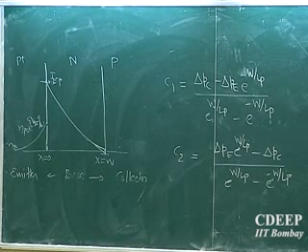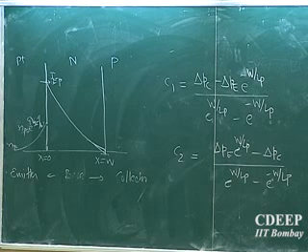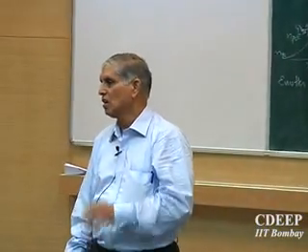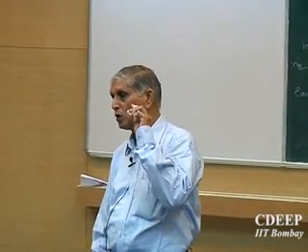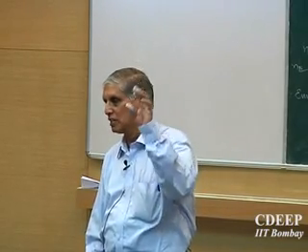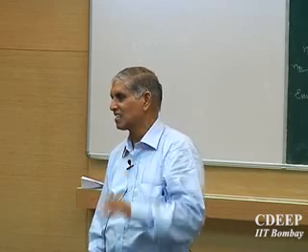Whereas in this case, which current is dominating? The minority carrier current is dominating. Why do I keep saying minority? Because if it is an NPN transistor, the minority current is due to electrons, because electrons from the emitter will go to the P base, so we call it minority carriers. Instead of saying electron and hole, we say minority carrier transport dominates the bipolar currents. Is that clear? Whereas in MOSFETs or other FETs, it is the majority carrier transport which dominates.